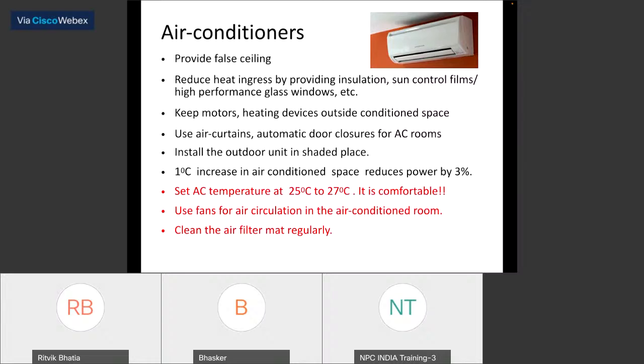At many times people ask us whether the use of fans for air circulation is needed in an air conditioning room or not. This is a debatable thing, but let me be very clear: because of the fan in the room and the velocity of the air, a lot of energy is saved while giving comfort to the body. You can raise the set temperature by 2 to 3 degrees by using a fan and be more comfortable at your place. So it is now being suggested everywhere to use a fan for air circulation in the air conditioning room.